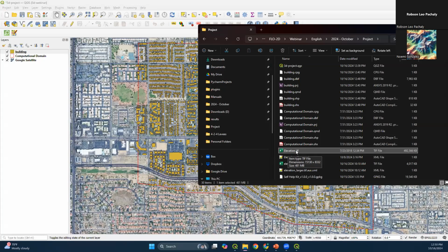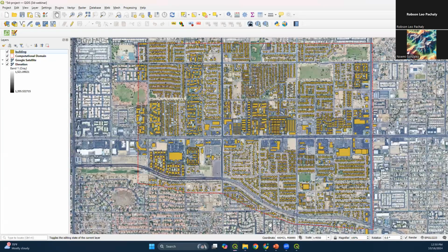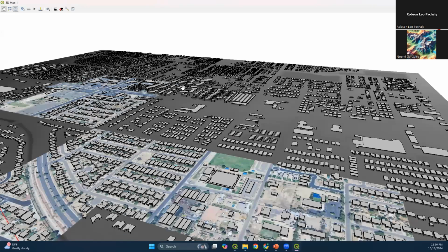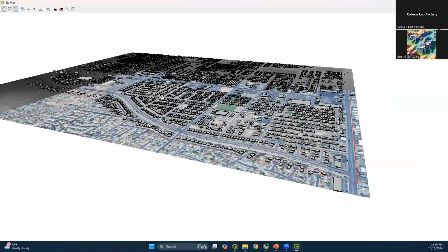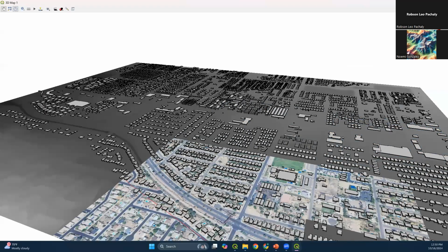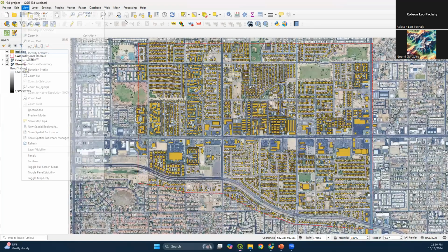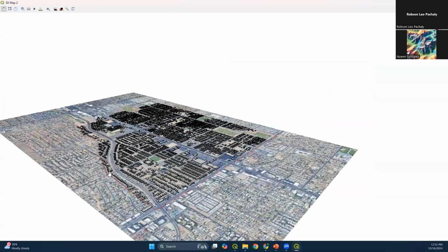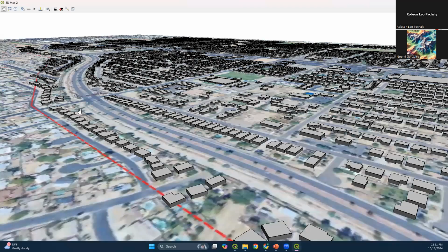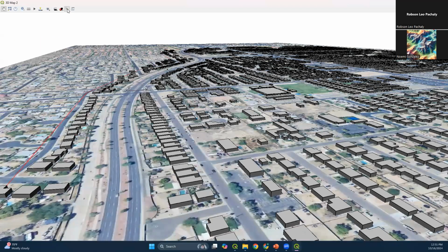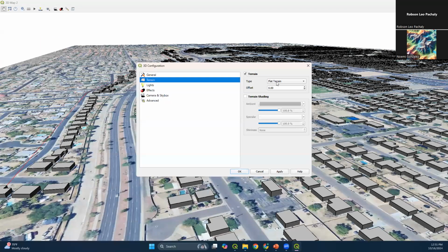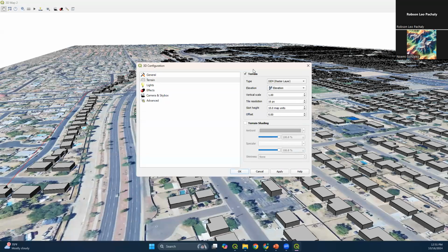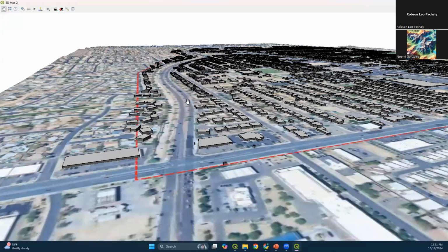Let's start with this guy here. Just drag and drop. Let's move this to the bottom. So if you click here again, it's a little bit buggy, that happens. So you can just exit there and create a new one. That's totally okay. Expand, and then you can see that we have some elevation here. No, we don't have elevation yet. You need to click here and go to terrain, DEM, and select the elevation and click OK. Yeah, now we do have some elevation here.